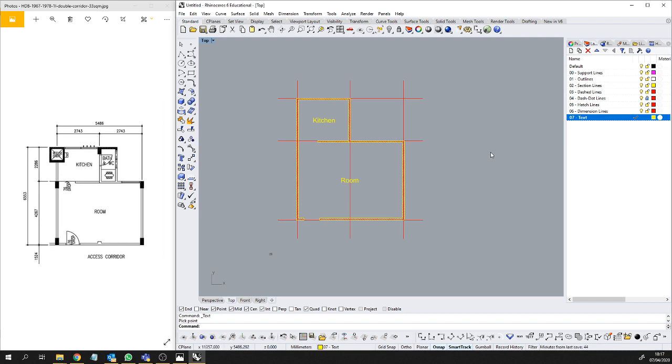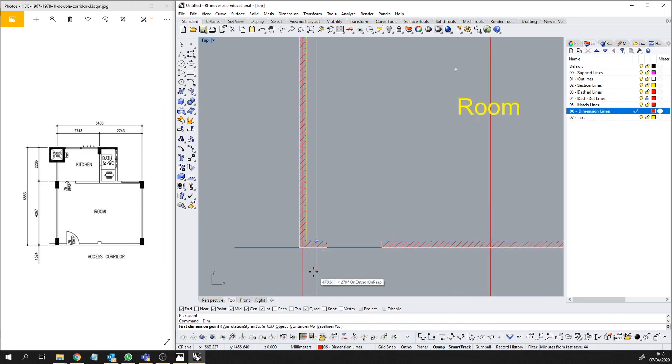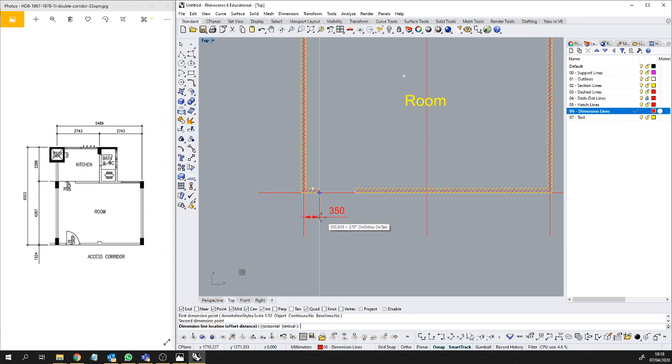Then the final thing is the dimension lines. For the dimension lines, we take the dimension lines as used here, but generally I like to have the dimension lines at the bottom and here on the right. So let's do that. We go from the smaller dimension lines inwards to the bigger dimension line outwards. So we type in the layer of dimensions. We click on the first one here. Then we go to the grid line. We go to the first part, and then we pull it outside.